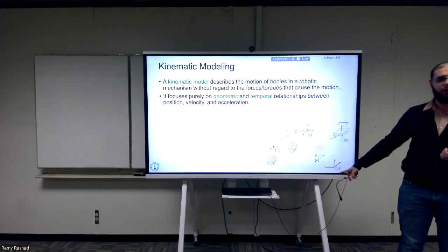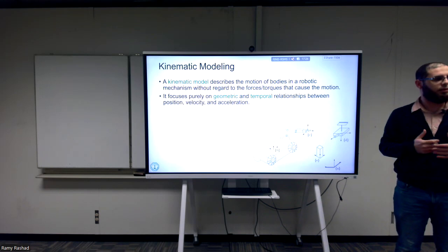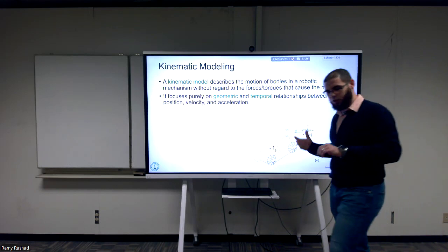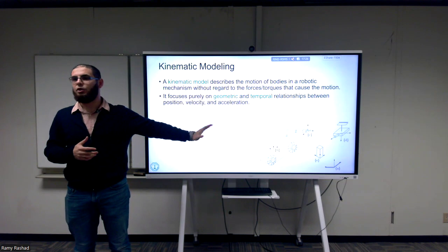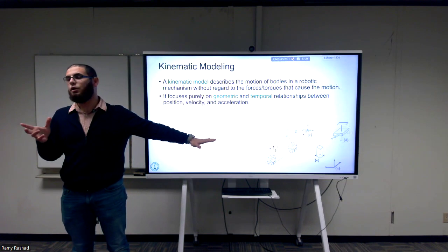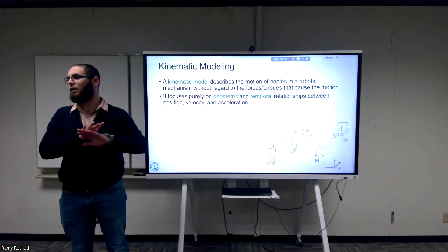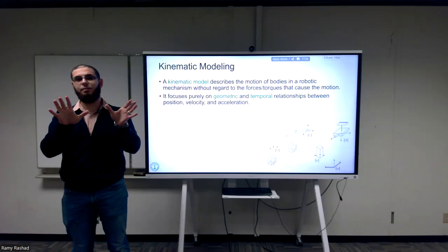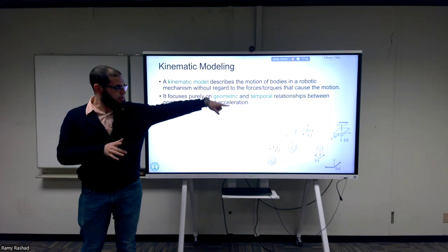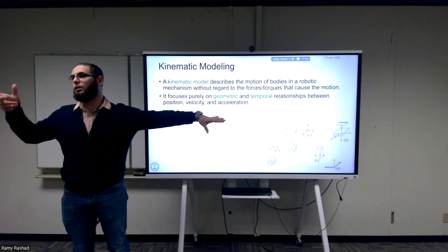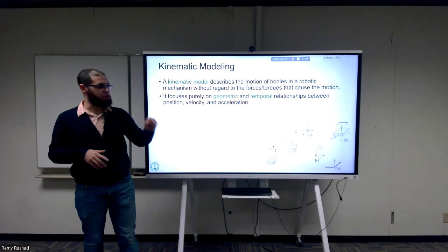We always have a stationary frame, and then we have some sort of motion capture system or camera that is measuring some information. It's very important, and this is one of the assumptions we mentioned last time, to have a stationary reference frame, because it usually defines your home configuration, your home pose, such that when we say identity matrix, whether a 4x4 or a 3x3 identity matrix, we mean that these other frames coincide with this reference configuration, this home position, this stationary frame. That's why it's very important to have the stationary frame.